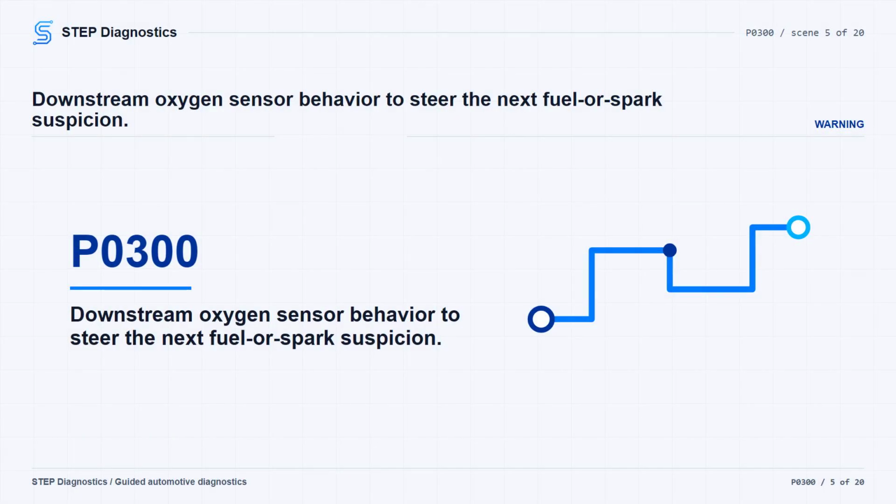A downstream oxygen sensor staying low points you toward a lean condition, like lack of fuel from a plugged injector or fuel system issue. A reading staying high means the catalyst is being loaded with too much fuel, which can happen from lack of spark or a leaking injector. Also remember, on a severe misfire, the PCM may shut off injector control on the affected cylinder to protect the catalyst. That can make a high-load misfire look like it is still there at idle, until the rev counter resets.